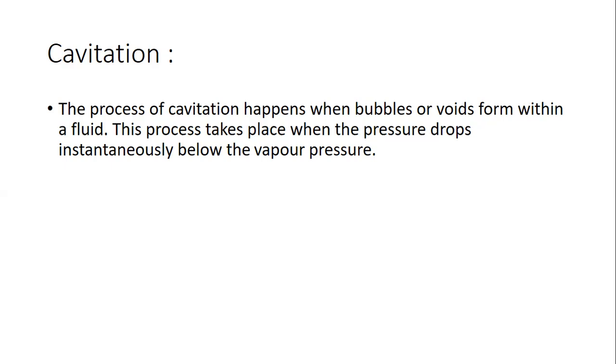This phenomenon takes place due to the variation of the pressure drop in the fluid. If the fluid pressure is below the vapor pressure, then cavitation takes place, and air bubbles arise inside the fluid.